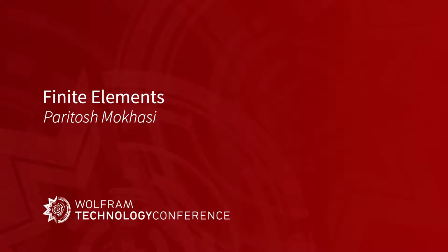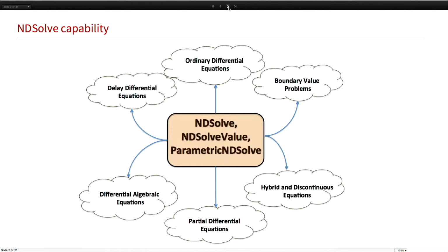So let's get started on finite element methods. For those who are new to NDSolve, NDSolve is one of those super functions in Mathematica that allows you to solve a large variety of differential equations. It could be boundary value, ordinary differential equations, DAEs, what have you. And I'm going to focus on partial differential equations and how finite element methods are used to solve PDEs.